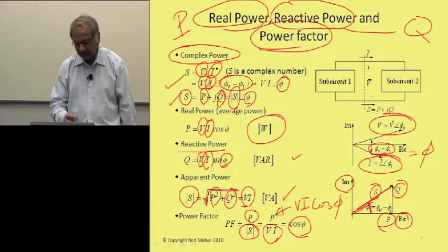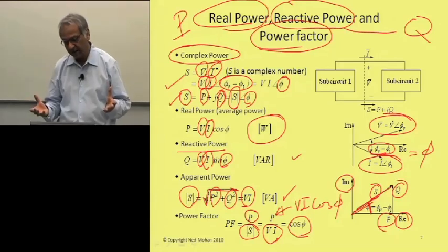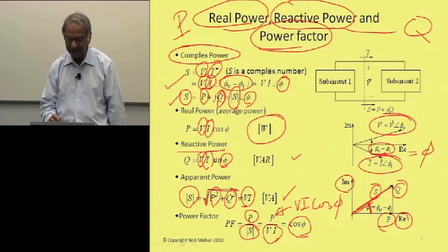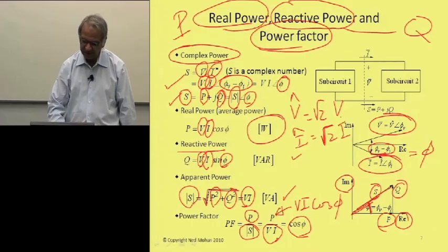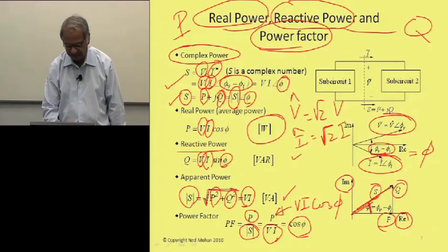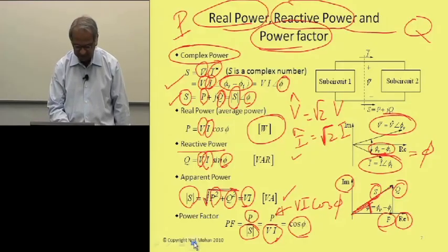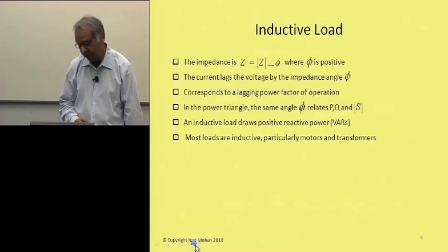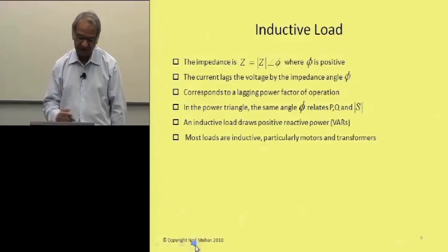In this slide, everything was done in terms of RMS voltage and RMS current, but we could have done it in terms of peak voltage and peak current, recognizing that peak voltage is just the square root of 2 times the RMS voltage. Similarly, the peak current is the RMS value times the square root of 2. This is true only of sinusoidally varying quantities. We can work with RMS or with peak, but in this course, mostly we will deal with the peak values as defining the amplitude of the phasor expressions.